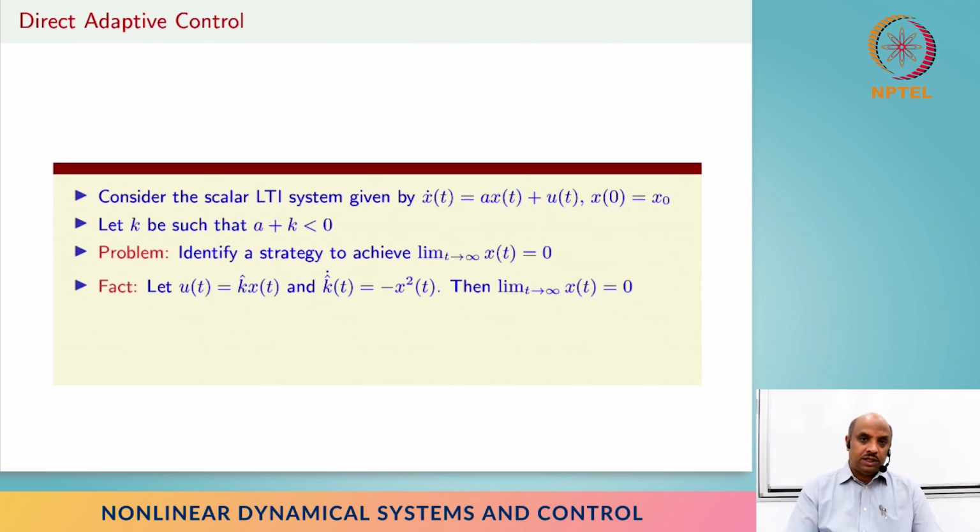And the extension of that is, if there is a stabilizing controller, it will be some kind of function over the states, and any function can be approximated by a neural network. Therefore you can search for the weights of the neural network and then hopefully stabilize the system. That's the ultimate extension of direct adaptive control. These days, if anybody is using learning techniques, that's the philosophy everybody follows: I'm going to learn what should be the stabilizing controller, right?